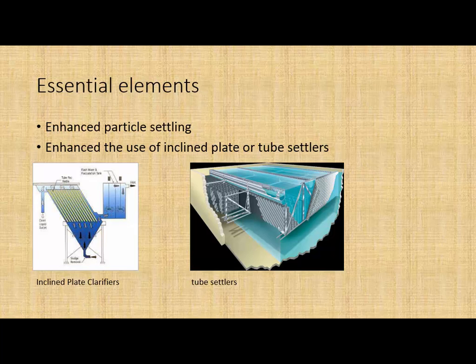And the essential elements of high-rate clarification: the first is enhanced particle flocculation, like this. And then the enhanced use of inclined plate and tube settlers. It's all combined from the three types of basic clarification.